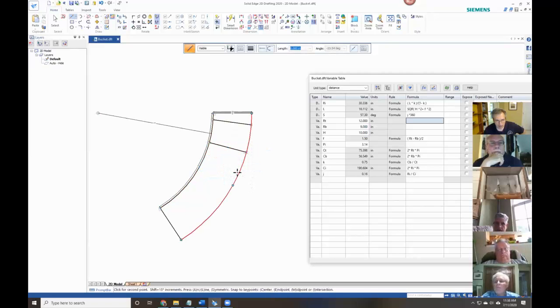And you can see, because I have this perpendicular thing set, if I draw it anywhere close to being perpendicular, it's going to let me know and keep that relationship. Every time it's trying to keep it tangent, and that's a problem for me. So I'm going to go up here and turn that off. And I don't want it to go to the midpoint or to the ends. I'm going to turn those off temporarily.